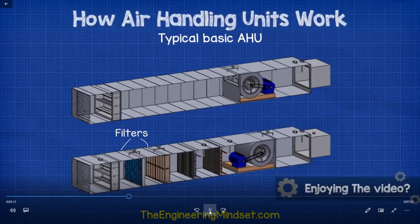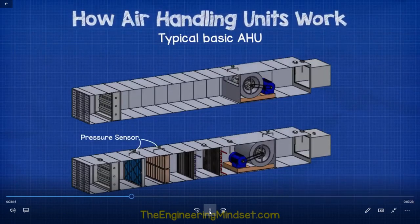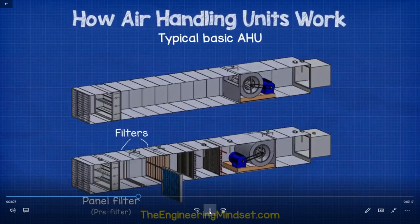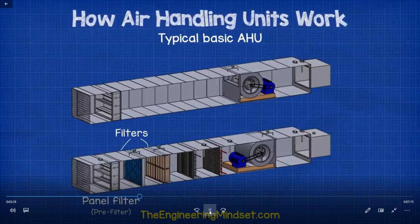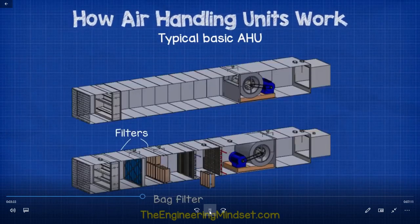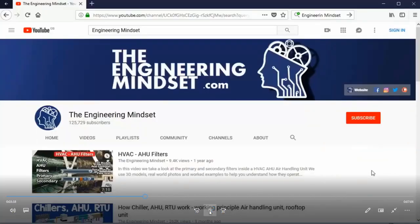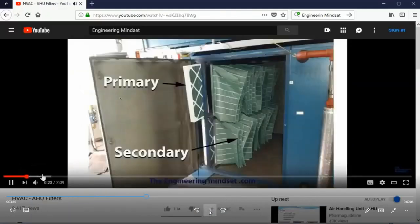Across each of the filter banks we'll have a pressure sensor. This will measure how dirty the filters are and warn the engineers when it's time to replace the filters. As the filters pick up dirt, the amount of air that can flow through them is restricted, and this causes a pressure drop. Typically, we'll have some panel filters or pre-filters to catch the largest dust particles. Then we'll have some bag filters to catch the smaller dust particles. We've actually covered AHU filters in great detail previously, links in the video description below, do check that video out.